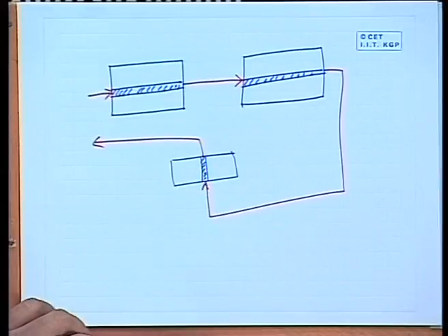This helps you in saving time in testing, in the sense that, see, the test generation and fault simulation algorithms, they are pretty complex. They take time which is more than of the order of n square, where n is the number of gates. So, if you can break the whole circuit into a number of smaller circuit and apply these to the smaller sub circuits, then the total time that you require will be much less in general. Okay. So, that is why this kind of a divide and conquer approach helps in reducing the total time that you need for testing. Okay.